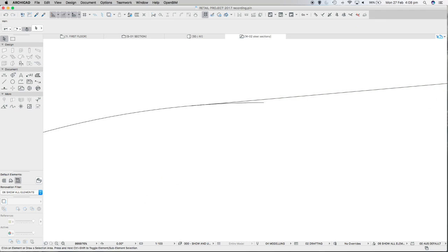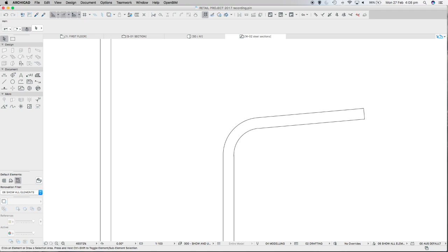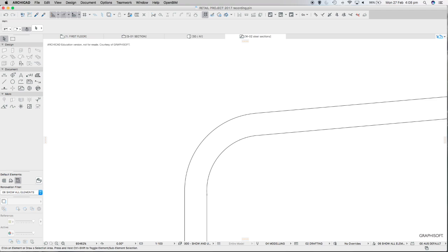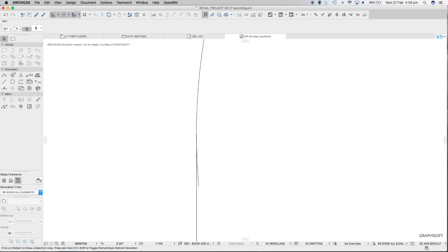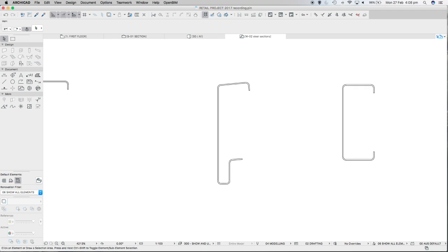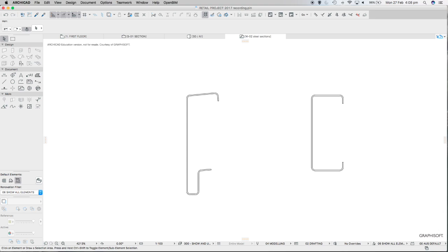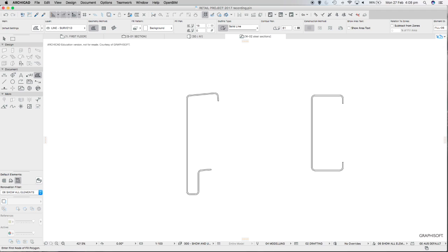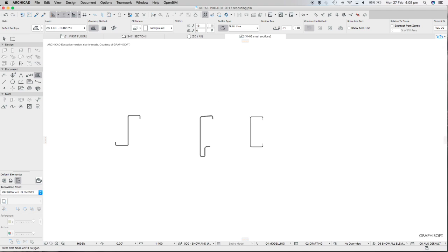In my case, there's a little bit of trimming to do there, and that's because this circle was not part of the rotate, but this circle was part of the rotate, so there'll be a little bit of trimming to do here. You've got to get those perfectly trimmed. Now I can put my fill back in. So I'll go back and do the fill tool again, click on the fill, just make sure you haven't got show area text, click on the magic wand and click part of the line there, and it should have placed a fill for the whole line there.